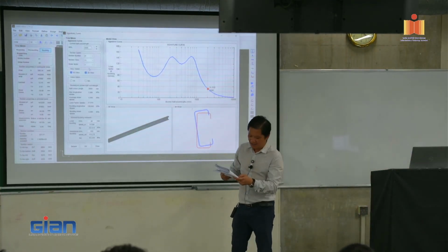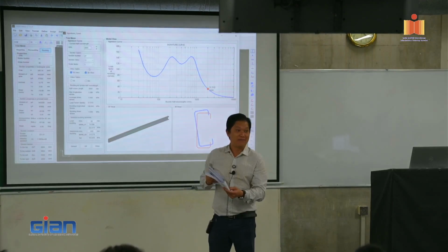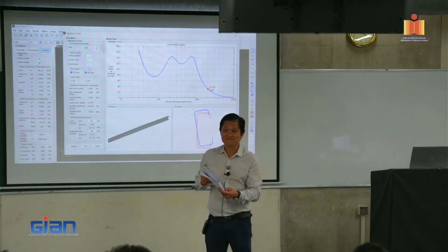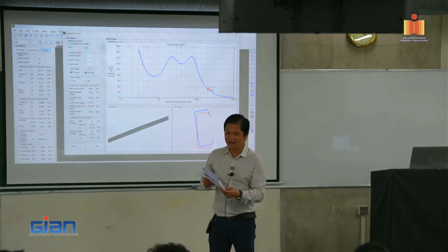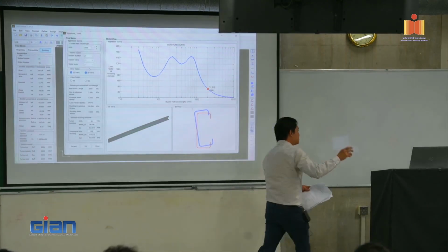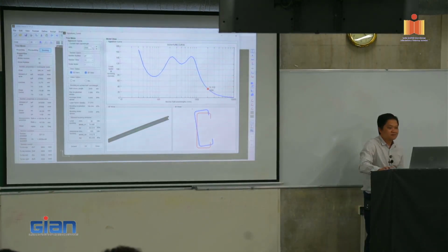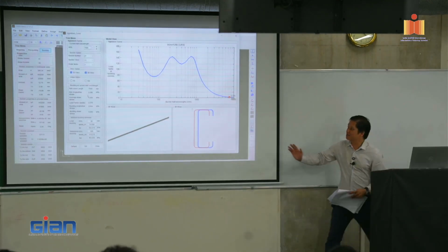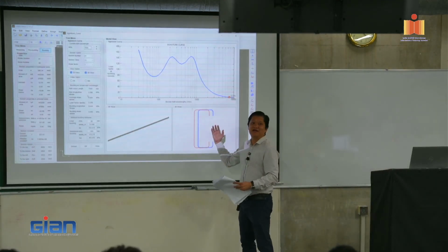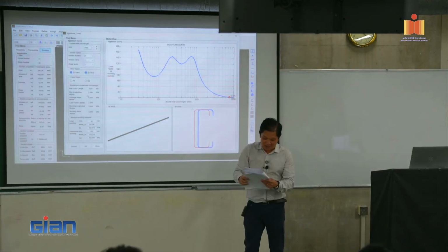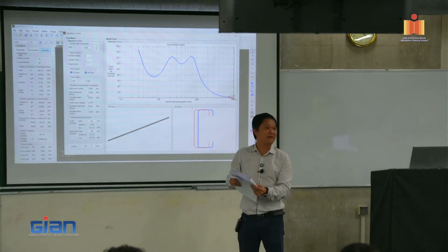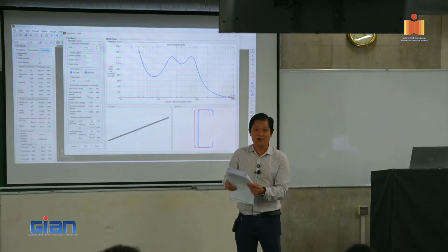So that is where the equation FOZ will come in. It will be smaller. Yes? All right. Now, if you increase the length to 8,000 or something, it just buckles in pure flexural buckling. So that's why the equation FOY will come in. So that is why we choose the smaller one.